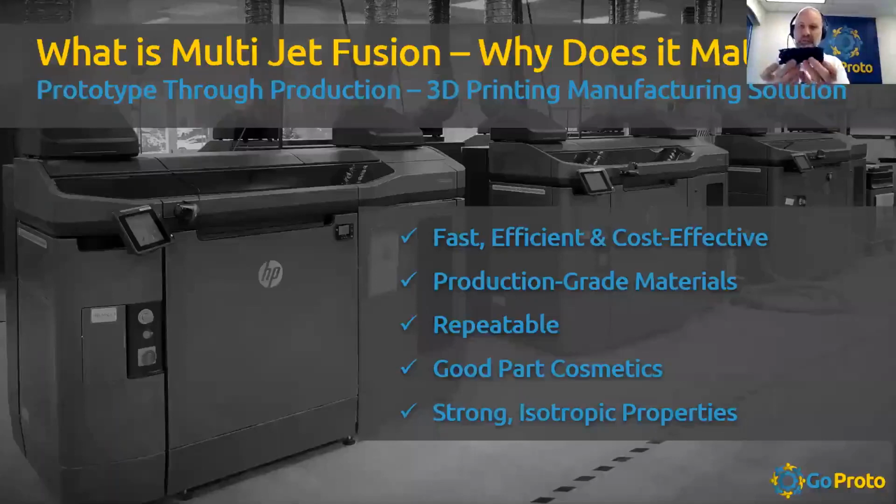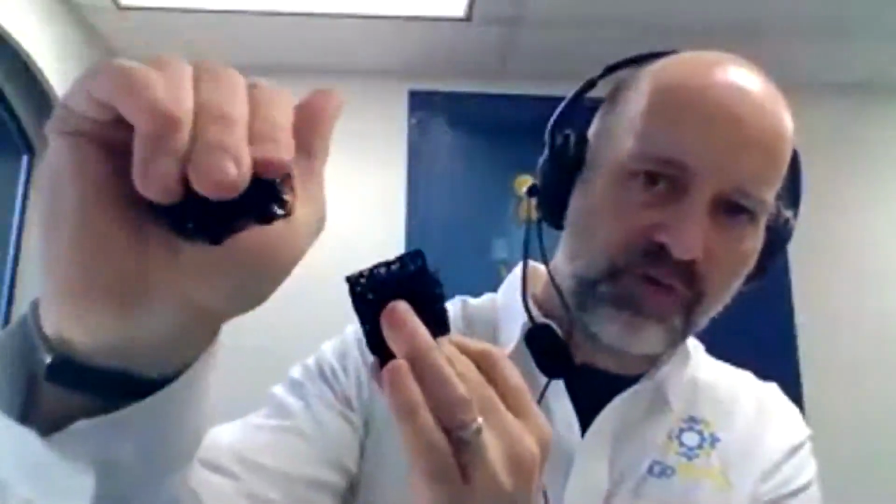Also, Kristen, I'm showing three lattices here, 3 cubes. You can vary the shape within the part. These are 3 different little cubes that have different shapes so that you can get different performance out of it. With elastomer parts, you're looking for the Goldilocks softness, the Goldilocks performance, right? It needs to feel just right. It needs to give enough to allow assembly, but be rigid enough that it holds its shape. Often that can be achieved by different shapes, and you may incorporate different shapes in your single part.